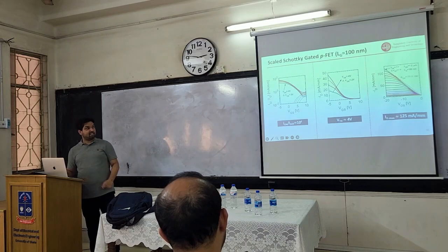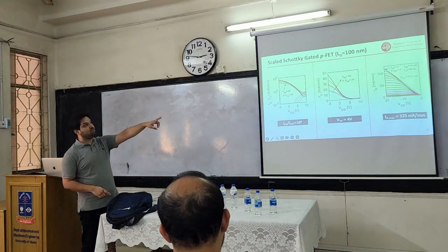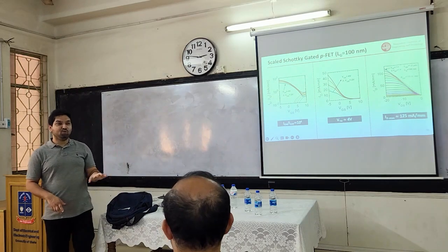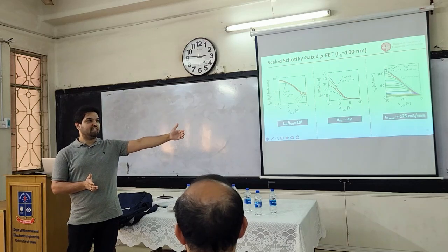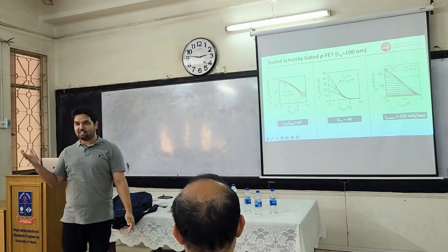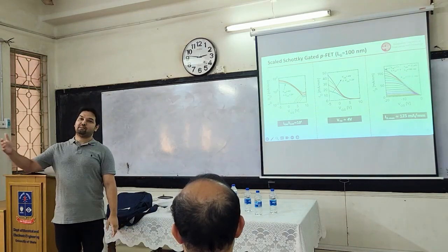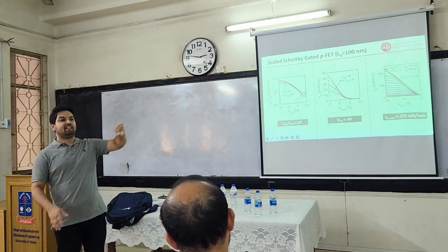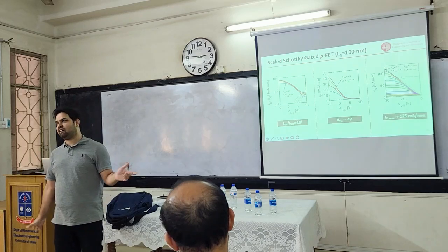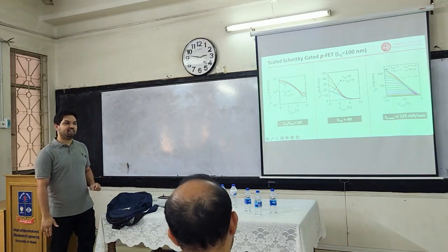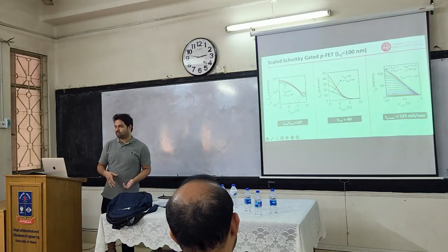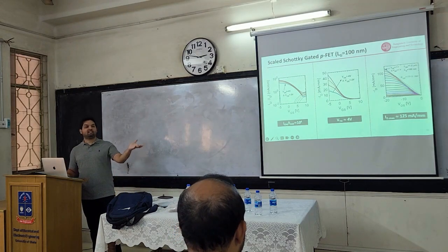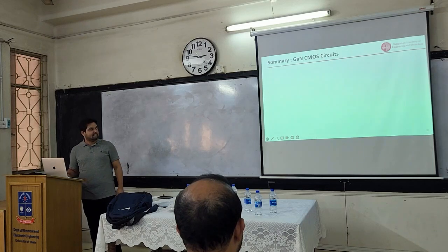And with 100 nanometer channel length, we got more than 100. This is a planar device, this is not a FinFET. So if we can do FinFET with this process, ideally you should get more current. Actually we did that, but that was after my PhD. This was my last paper. After my PhD, one guy did this, and he got around 500 milliampere current, and we published it in IEEE. I was one of the authors. I already graduated, so I couldn't do that, but I had paved the road that you have to do this.